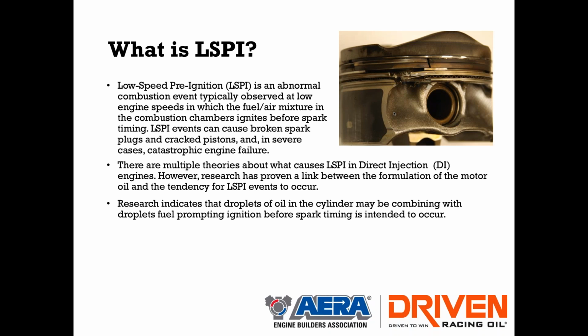So the biggest thing we're really seeing, and we've talked about it a little bit already, is that there's this definite link between LSPI and direct injection engines, specifically turbocharged direct injection engines, and it's severe. And there are a lot of theories about what actually causes LSPI. But what we do know for a fact, and there's research from several entities that proves it, is that the formulation of the motor oil has a direct impact on the tendency for these LSPI events to occur.